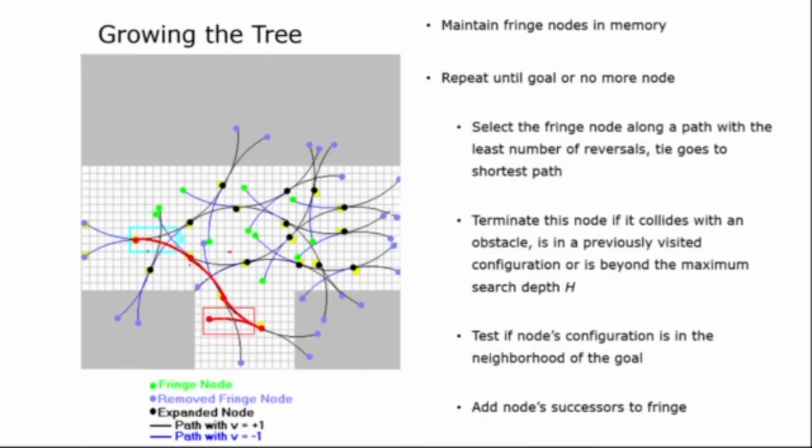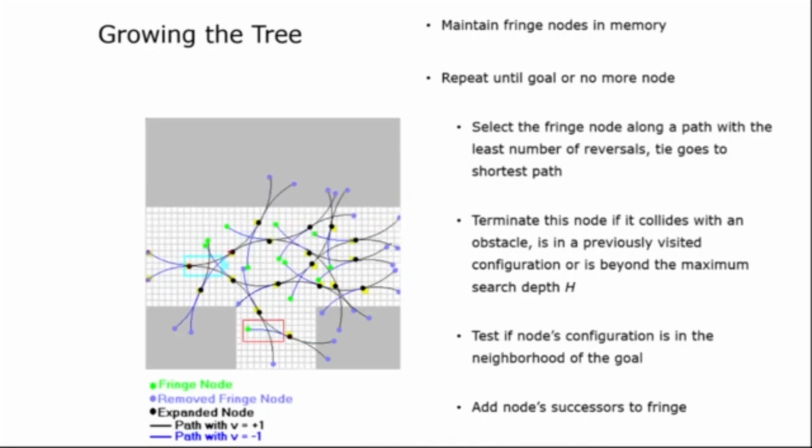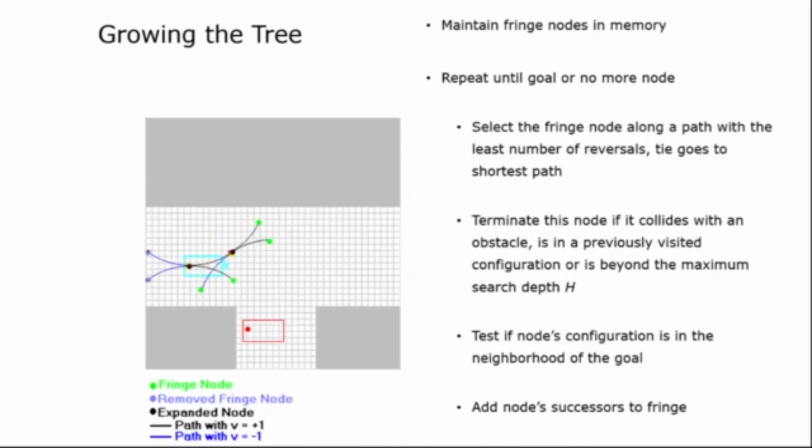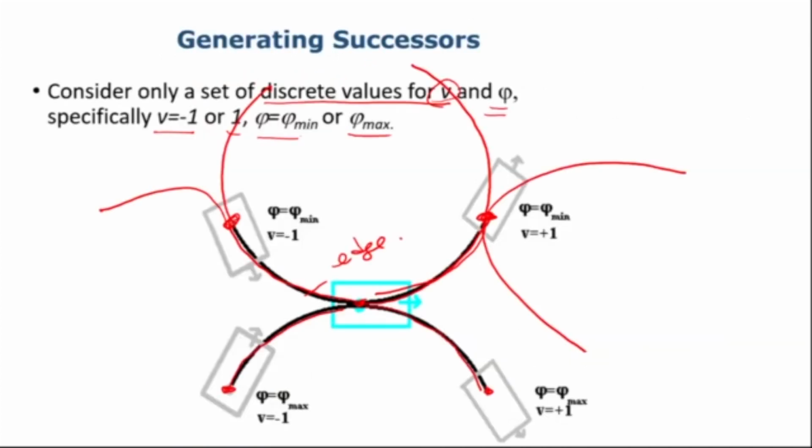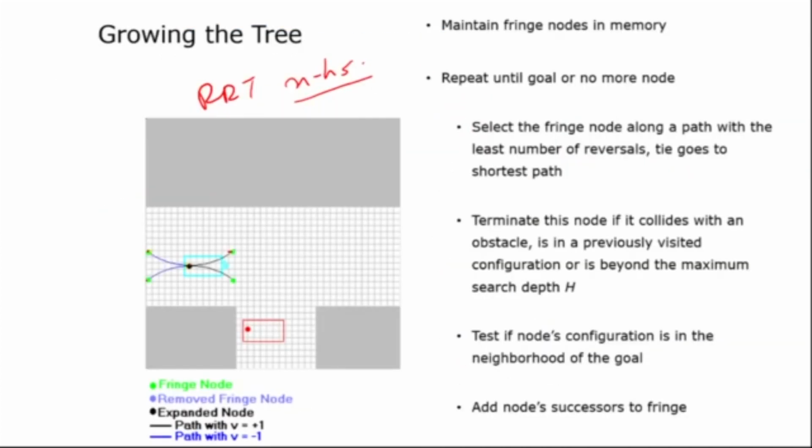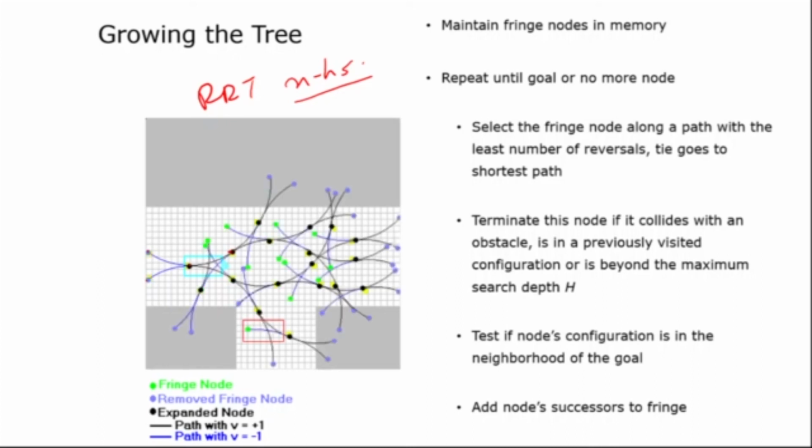So in the previous case, we were interested only in the case of a car, and the car was having a single non-holonomic constraint that it cannot go sideways. It's a velocity constraint, and we showed that we can have an automatic path planning method similar to RRT. So RRT for non-holonomic systems can generate motions of the car, which is going to take the car from one point to any other point simply by generating these possible nodes and then following it up with edges. So you can see that the whole workspace is being covered.